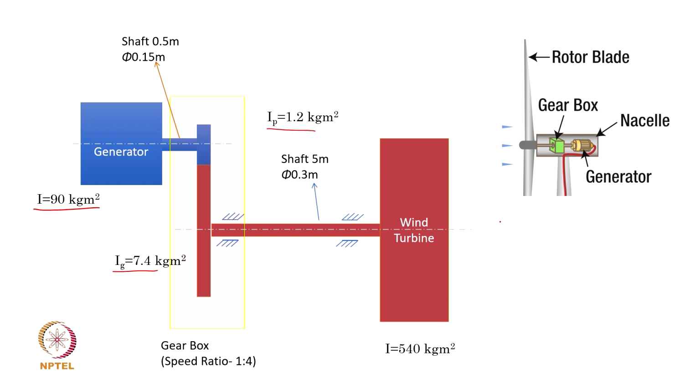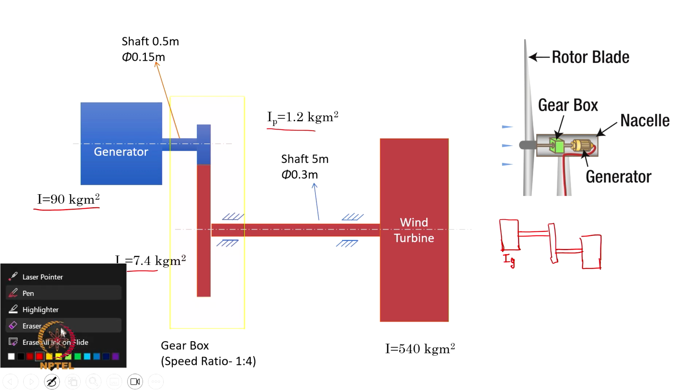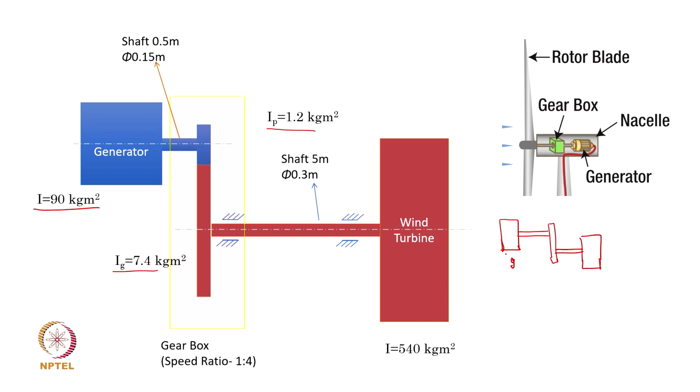Okay. So, what it then boils down to is you have a generator, and then that is connected through this gear pair to the turbine, and both of these inertias are sizable. So, as our approximation process, I'll write this as G, that is the generator inertia, and this the turbine inertia. Now, here is the catch, the inertias of the gear and the pinion being minuscule as compared to that of the generator and turbine, we can neglect them, and then what we are left with is obviously 1 degree of freedom corresponding to the generator, and the second degree of freedom corresponding to the turbine. Okay.